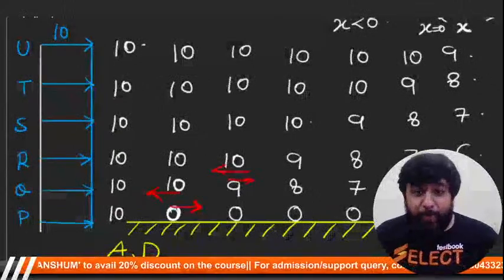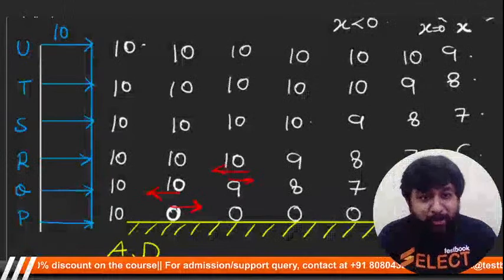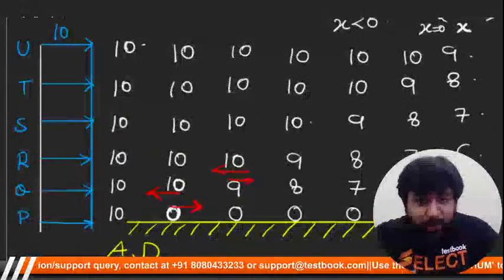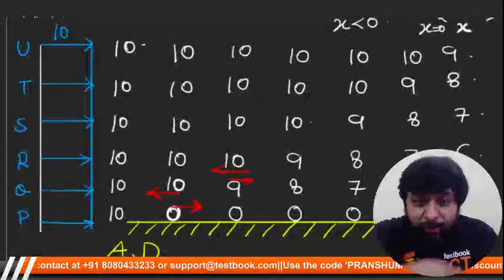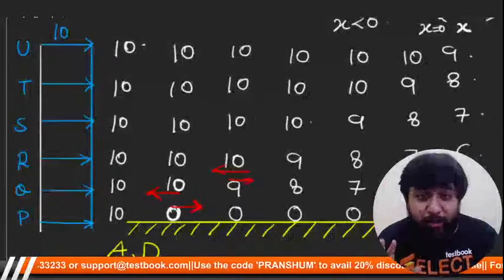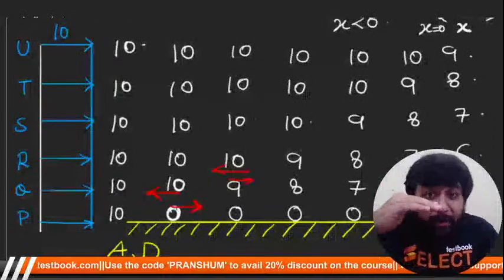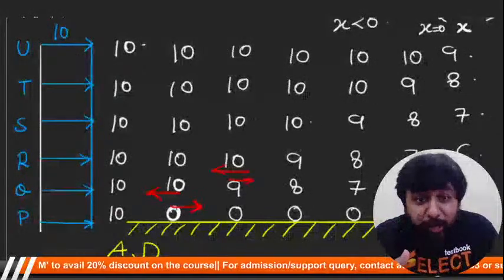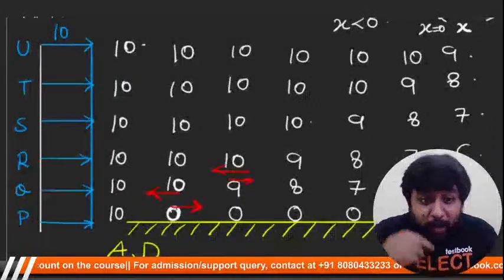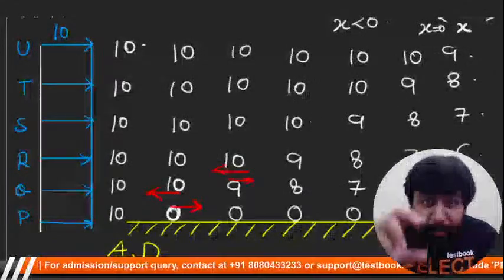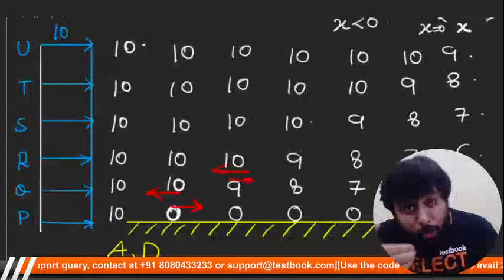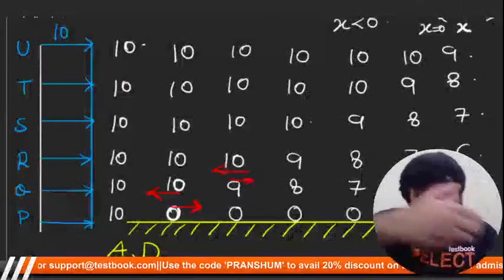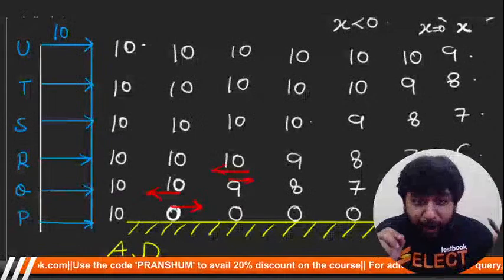So guys, water is moving over the plate, and we have shown the value of velocity at a point. When water moves ahead, the lowermost layer of the fluid comes in contact with the solid surface. It achieves the no slip condition, so it is immediately at rest. Now the upper particles are moving with some velocity, so there is a relative motion. With continuous deformation, because of viscosity, internal stress comes into picture. This slows down the second layer. Initially the second and third particles were moving with the same velocity, but when particle 2 slows down, there is a relative motion between 3 and 2. So there is a shear stress which slows down the third layer. Similarly, the third layer slows down the fourth layer and so on. I hope this is clear.